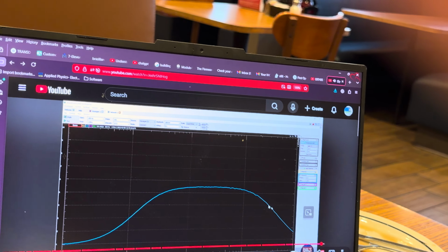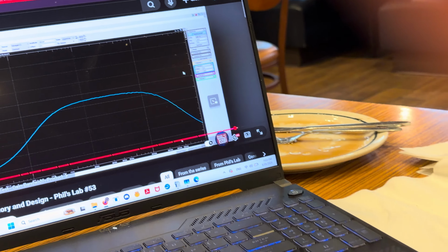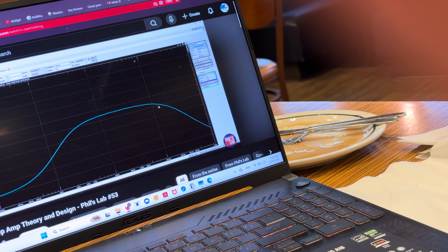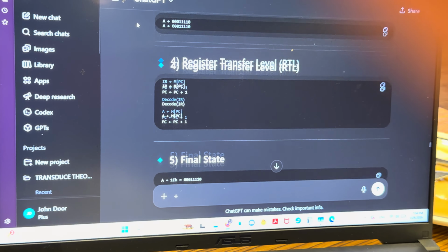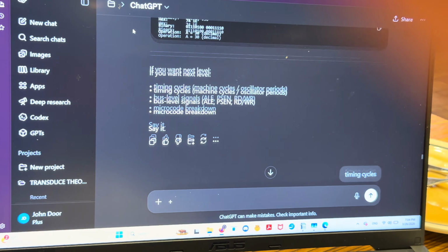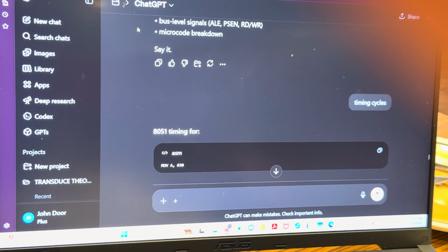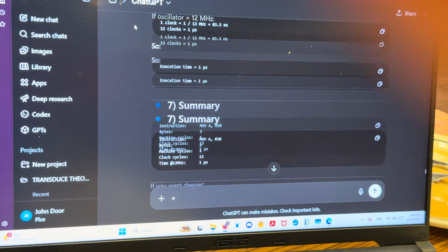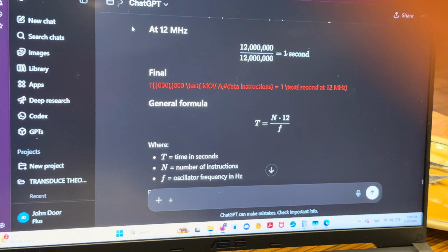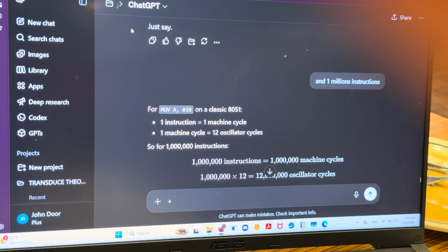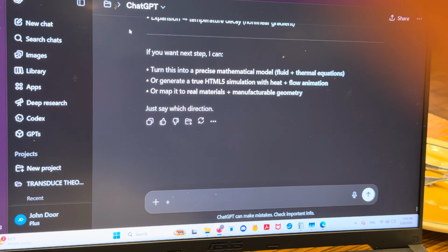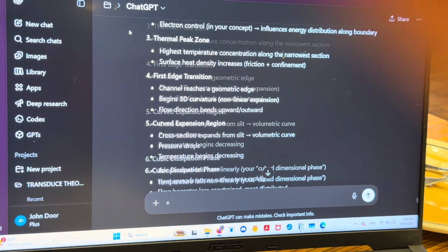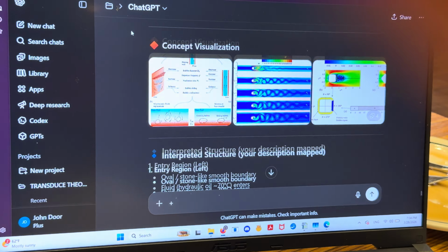So somewhere here is our new bandwidth, which is about 350 kilohertz. By increasing the gain of the closed loop system, I am sacrificing bandwidth. I can do that even to the extreme by turning the potentiometer all the way to the other side, and I get quite a lot more gain, to around 10 linear, but then of course I have a much lower cutoff frequency, something around 100 kilohertz. This kind of demonstrates the gain bandwidth product. So let's stay with this network analyzer and move our gain potentiometer right back to the center.